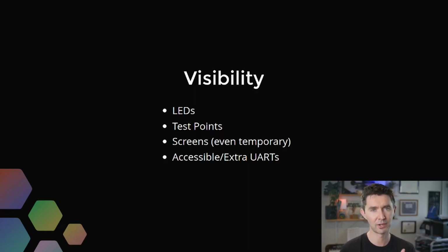Test points is another one where you need to be able to get at the different signals and have them very clearly labeled so that you know specific outputs when you're on your test and measurement equipment and stuff like that. I think screens, if you have the time and inclination, are a great way to have heads up insight into what you're looking at inside the hardware you're playing with. Even if they're temporary, right? They might be plugged into those standardized interfaces. You can always pull them off later.